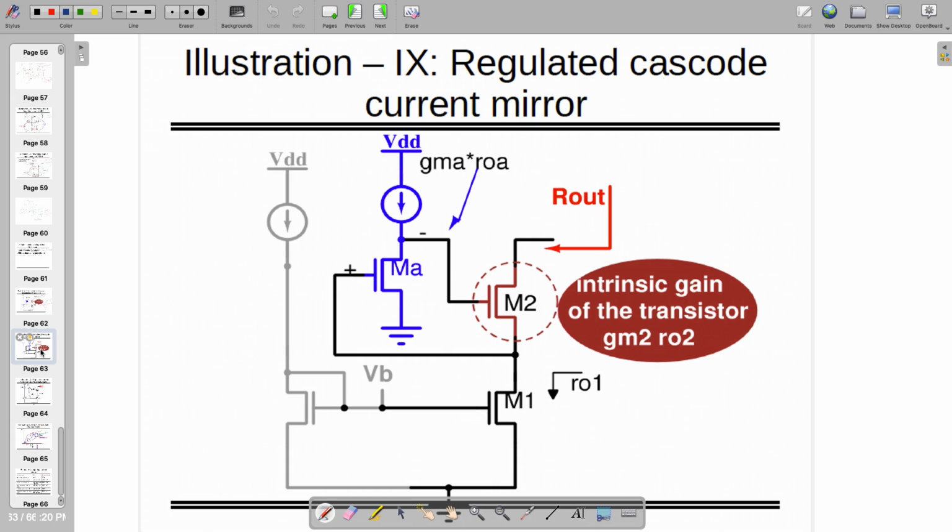And when we are saying common source amplifier, where we are keeping a current as a load, whichever current you like, you can keep that, whose looking-in impedance is infinite, because a current source always has infinite impedance. Then this particular configuration is going to give me minus gmA times roA, by the way. Okay, so that's a mistake over here.